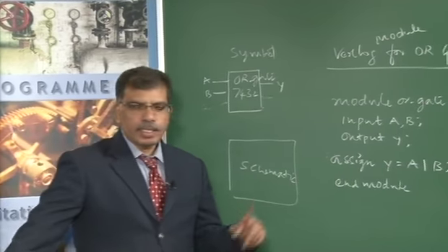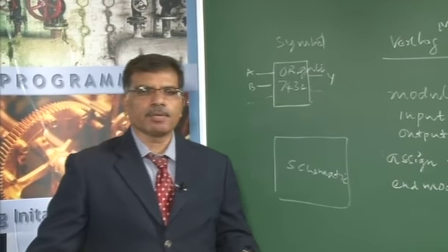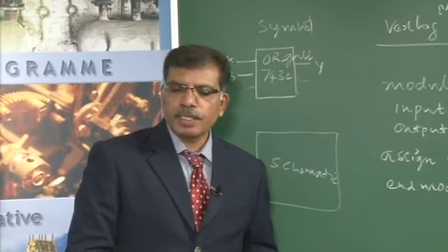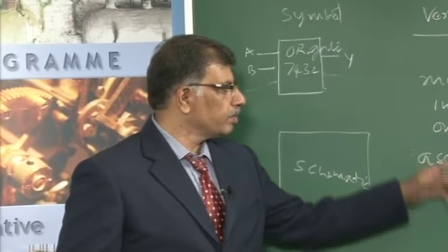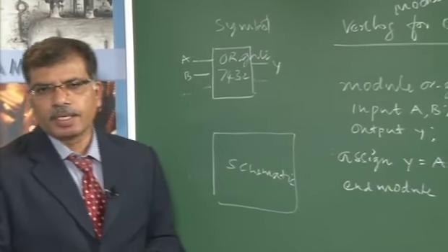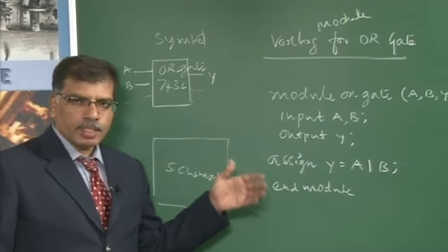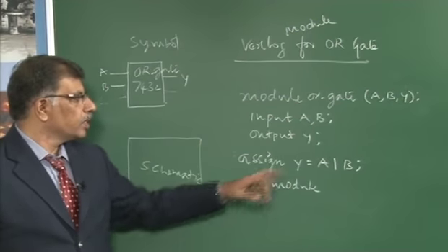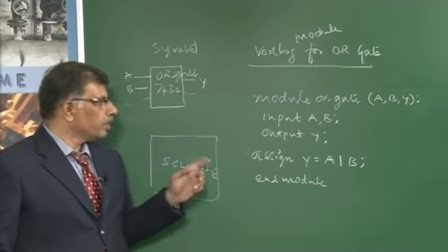One is by writing the test bench, another is by using the simulation software that is available with the software that you are using. In Xilinx, you have Xilinx iSim, which supports doing the simulation with respect to the model that you have written. So there are two ways of using it. One is by using iSim, you can force the value to these ports A and B, and you can check what output you are getting for a particular duration. That is one way of doing it.